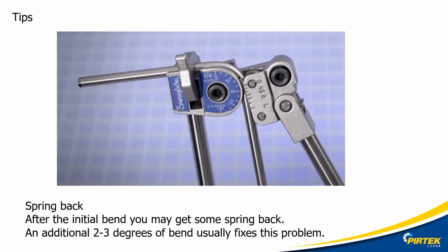Remember, if you do make a mistake and you reverse the bend, you could damage the structure of the metal, cause cracks or annealing or work hardening. So get it right the first time. If in doubt, chuck it out and start again. Another good tip is to always practice or test your equipment on some scrap before committing material. And don't forget, practice makes perfect.